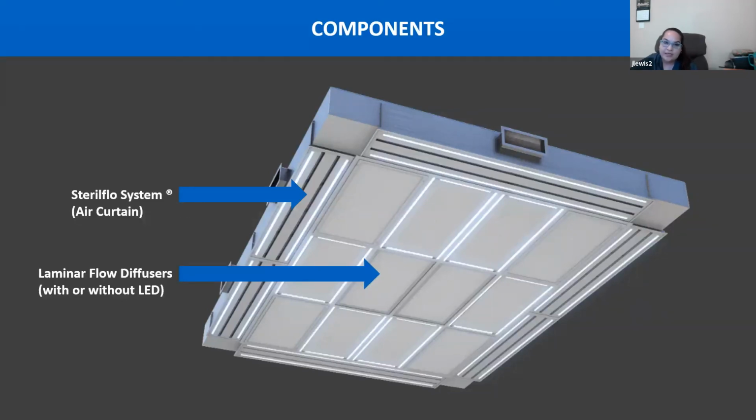So a mixture of the two is sometimes required, which is why photometric analysis, or seeing how much light you get at your operating table, can be useful, because you might not need them on every laminar. And then blank-off panels. Blank-off panels are usually for access above the ceiling, or if there needs to be anything else mounted in the ceiling, like booms.